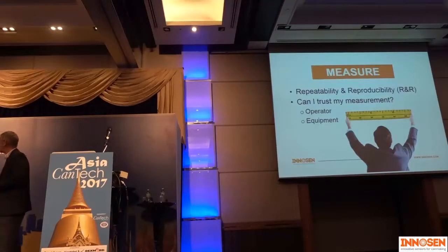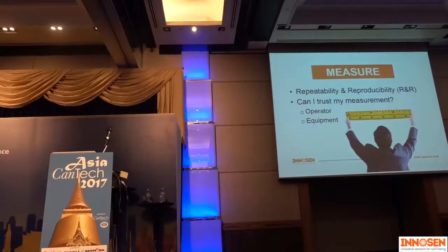And I have a very interesting example about this. We were heavily involved in film measurement of coating lines. And one of our customers had a huge problem with big coating thickness variations. The first thing they did is just introduce a logbook, a very simple thing, put it next to the coating line and told the operators, every time you make an adjustment, we want you to write in the logbook why you actually did it.